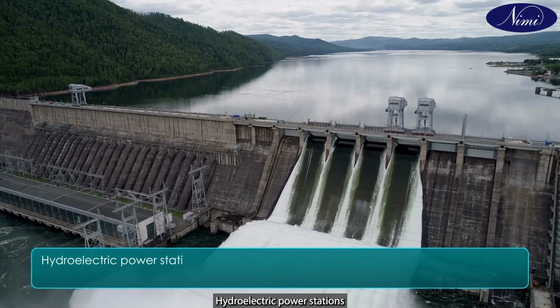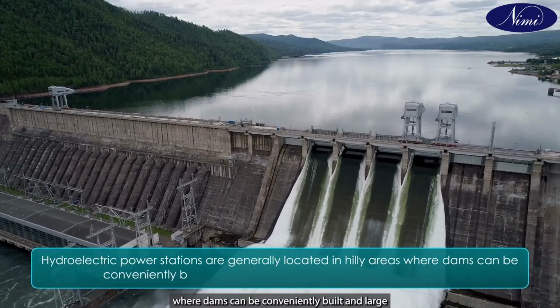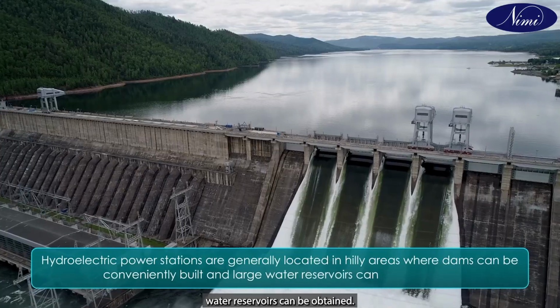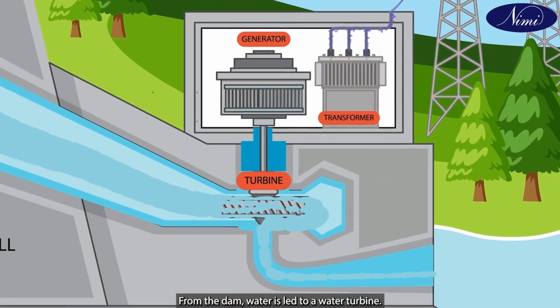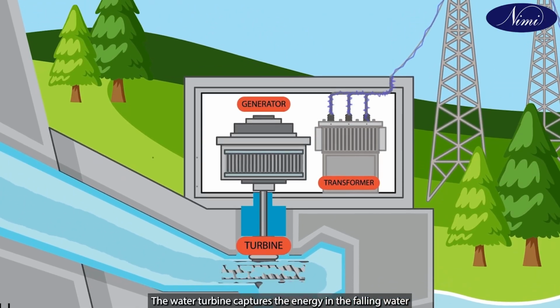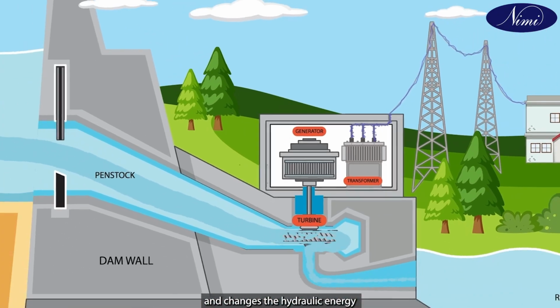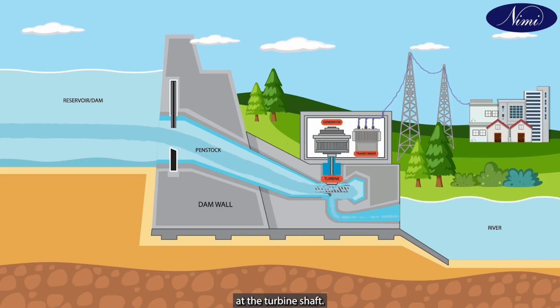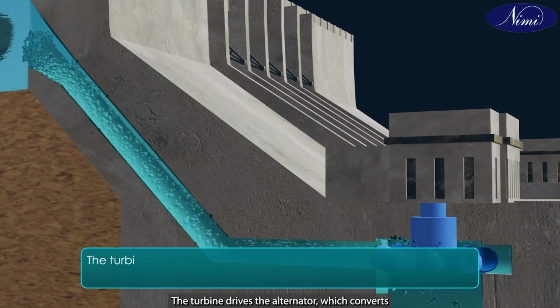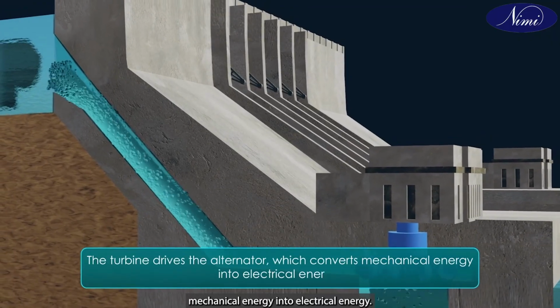Hydroelectric power stations are generally located in hilly areas where dams can be conveniently built and large water reservoirs can be obtained. From the dam, water is led to a water turbine. The water turbine captures the energy in the falling water and changes the hydraulic energy, that is, the product of the head and flow of water, into mechanical energy at the turbine shaft. The turbine drives the alternator, which converts mechanical energy into electrical energy.